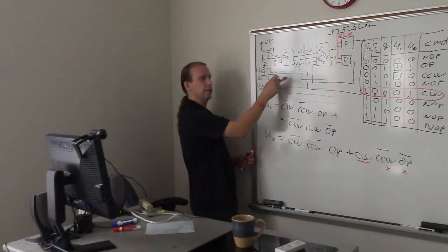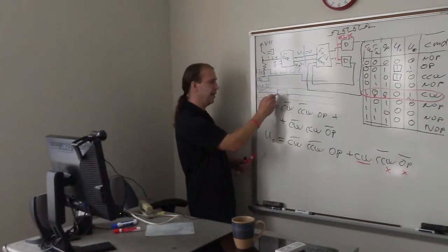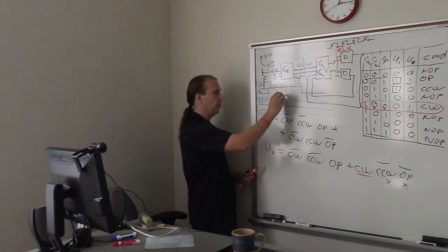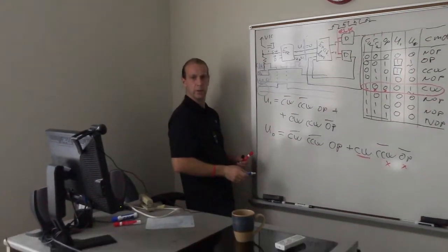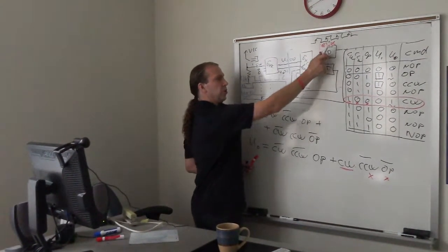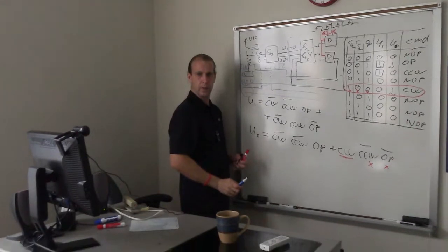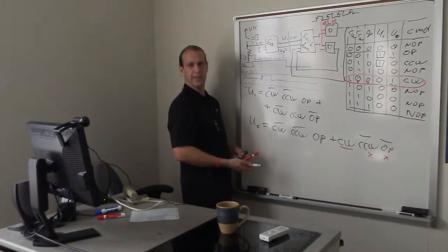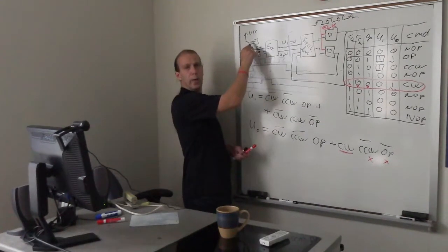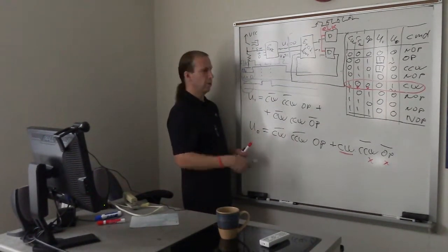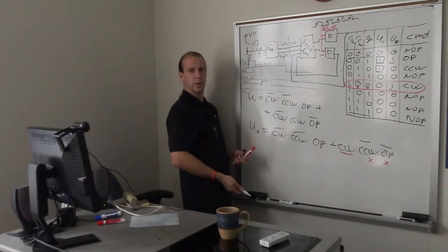But that long pulse needs to be translated into a short pulse, because a short pulse with the length of only 1 clock cycle will make only one single transition of these 2 triggers. Say if we were in state B, we'll just move to state C, and we'll stay in state C regardless of how long we keep pressing the push button. And once the button is released, it's going to stay in state C. Right.